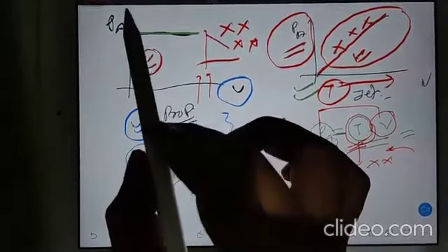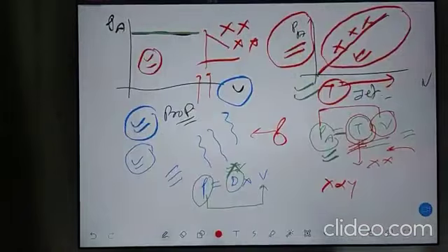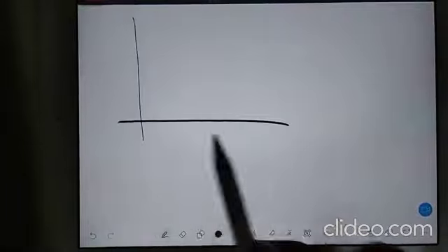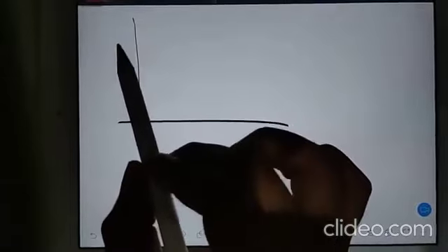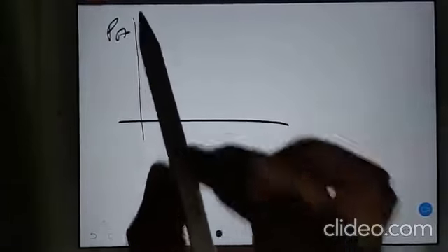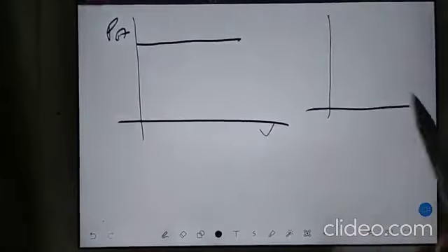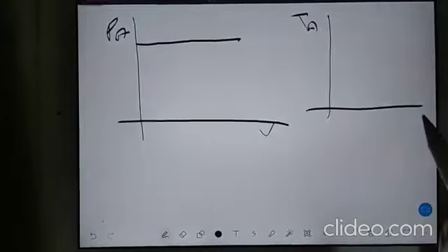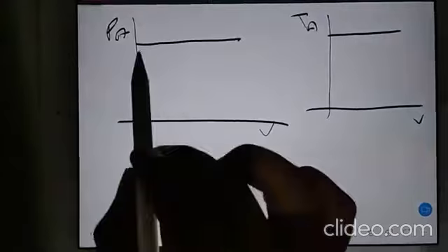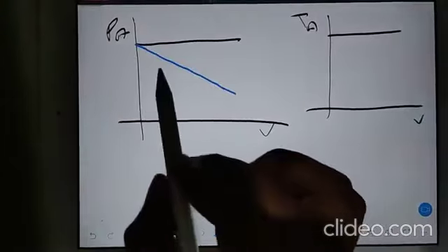Okay, now see overall how much you have to take from this in mind. Whenever there is a question about power available, quickly it should come in your mind. Power available is used for propeller engine and it is constant with velocity, and thrust available is used for jet engine, it is again constant with velocity, and thrust available decreases for propeller.